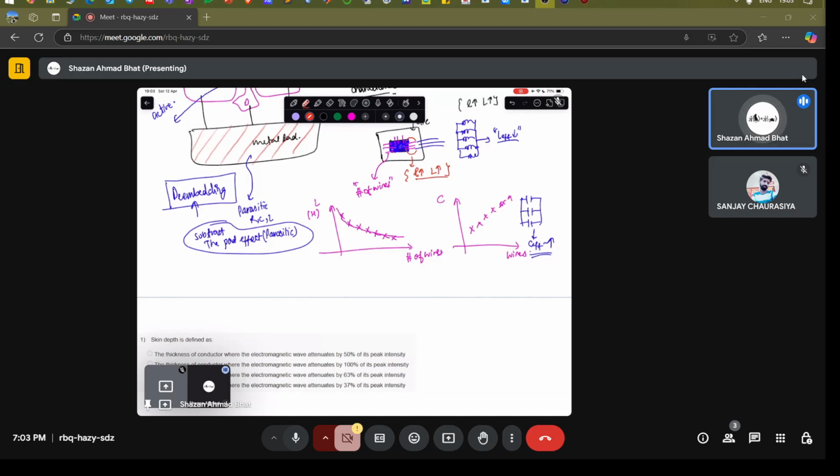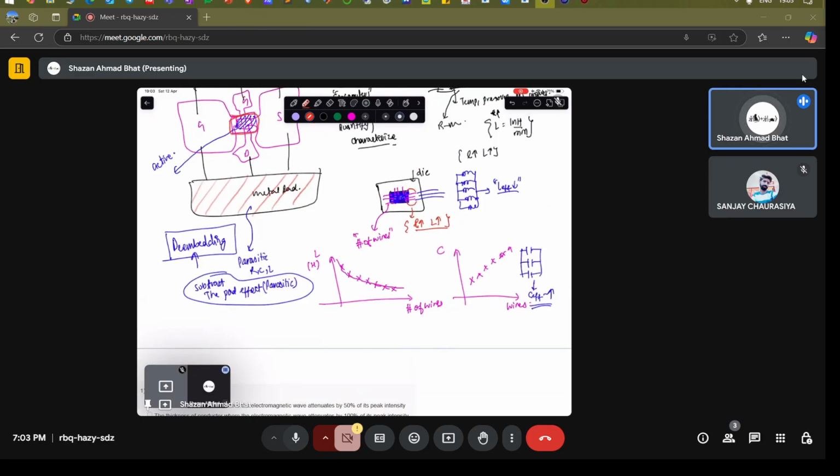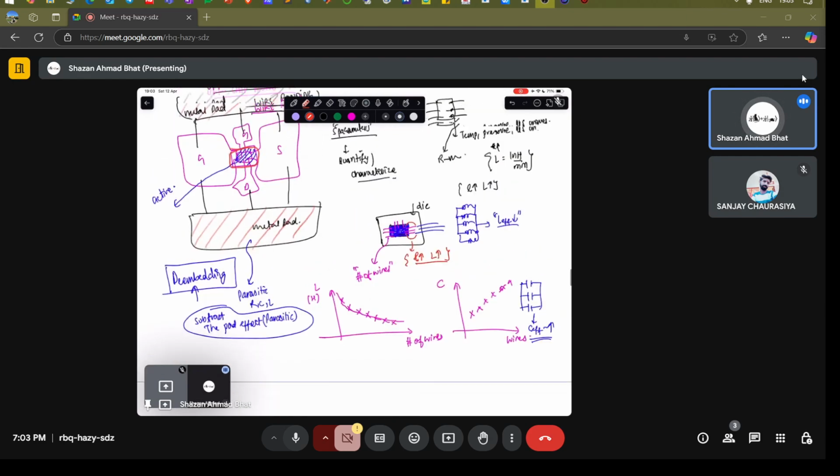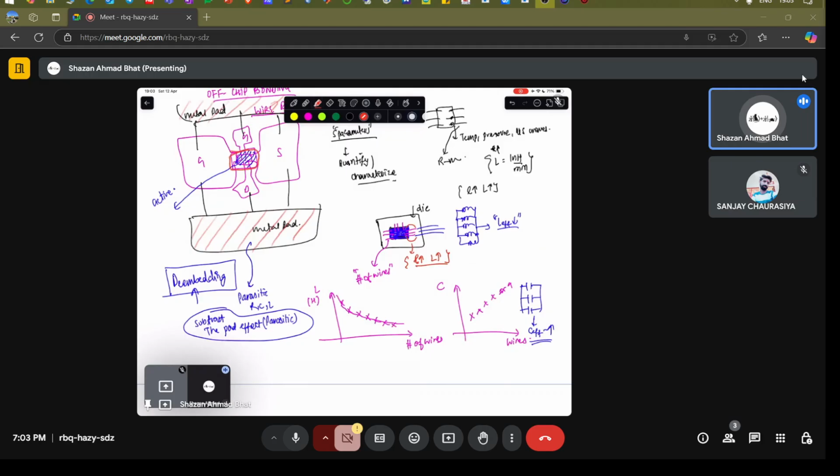Okay, and this is done for die, packages, wire bonds, boards. When you include the resistances of all those components, that particular process is called de-embedding. It's just like you're excluding the effect of those peripherals, so that you can consider only this particular active area, the active chip.